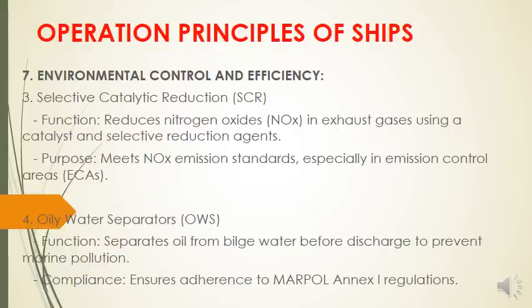Number 3, selective catalytic reduction. As the function, it reduces nitrogen oxides, NOx, in exhaust gases using a catalyst and selective reduction agents. So it meets NOx emission standards, especially in emission control areas.